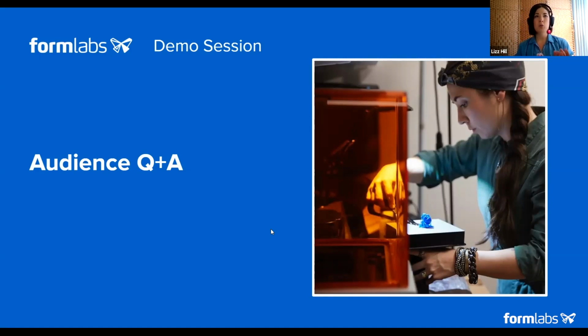And then from that, you could take that item and send it to a casting house. Or if you have access to casting yourself, you would put that through a typical lost wax casting process or investment casting. We have a different burnout schedule than you would expect to find with more traditional waxes that you would use for hand carving. So definitely consult our website for that burnout schedule that you may have to pass to a caster.